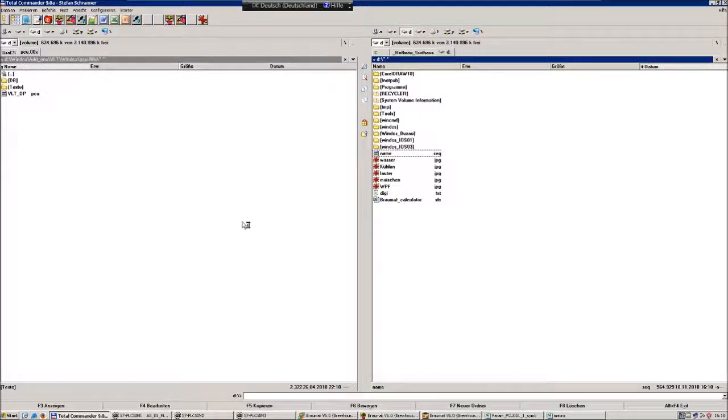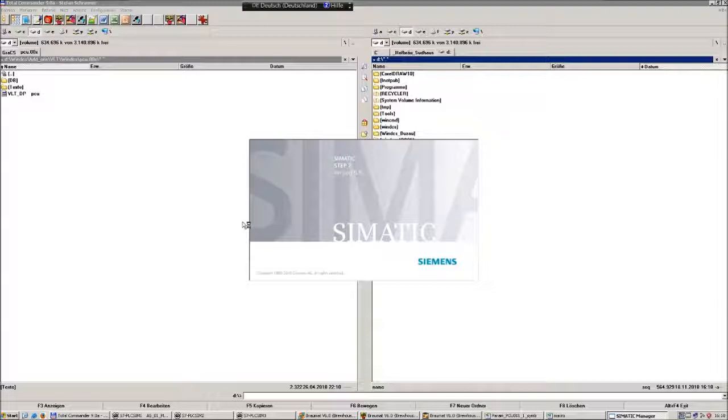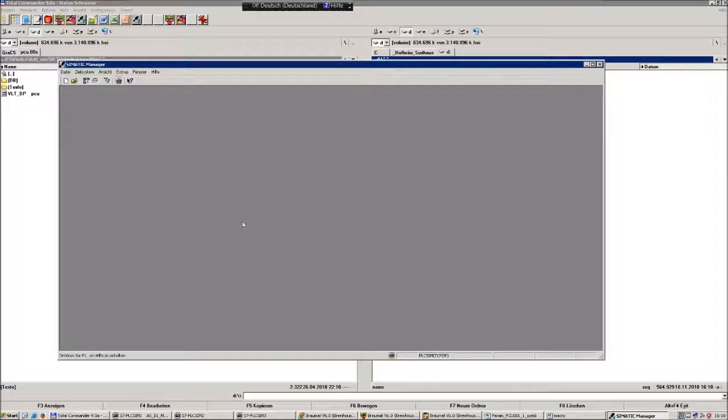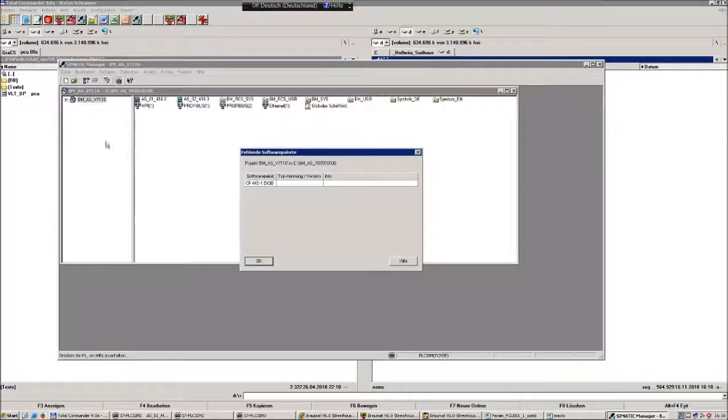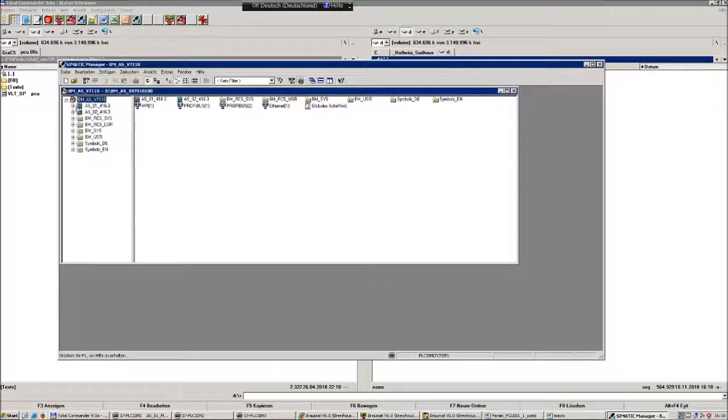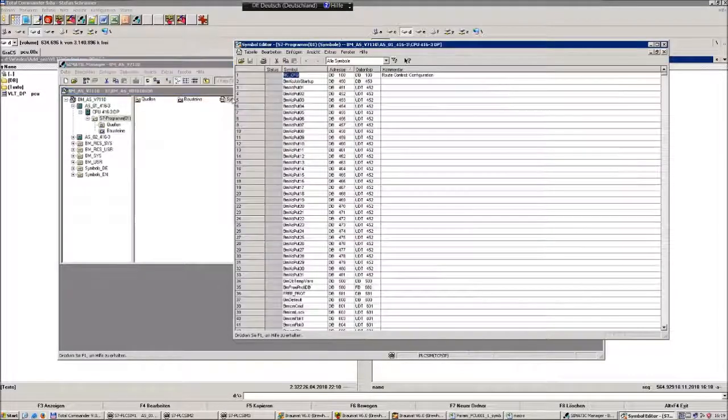Open my Semantic Manager. Take a little bit of time, and in the symbolic, during import, it's overwriting the existing one. You have to keep in mind that when a new file is coming, the existing one will be overwritten. That means if you have already done something in Semantic Manager with ICM, analog input, PID, then it's good not to export all of this symbolic file, only a specific part of it.